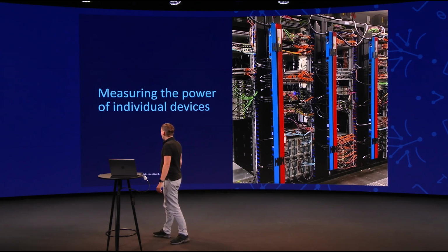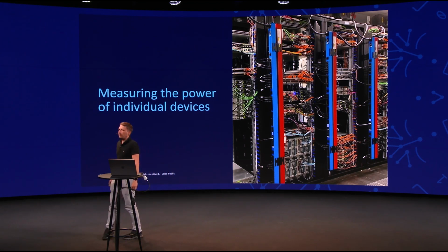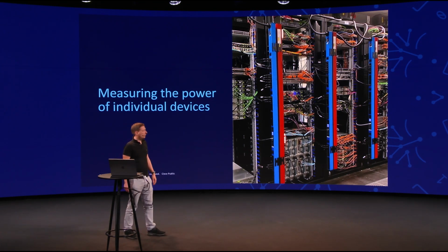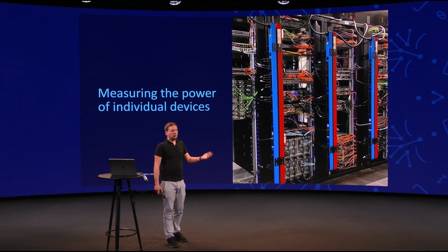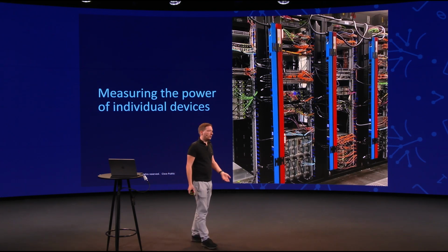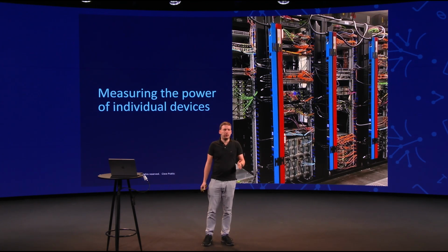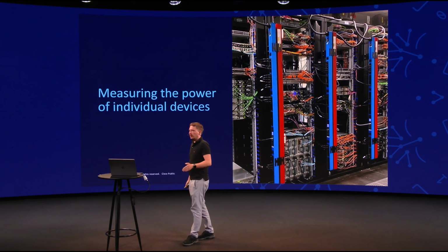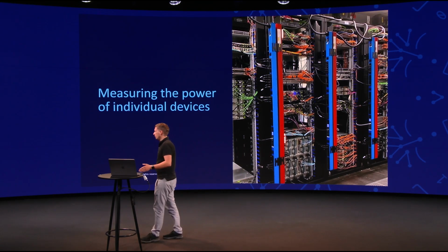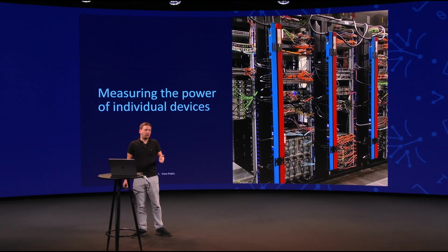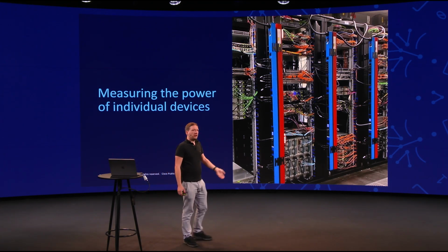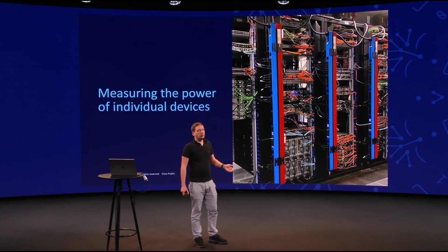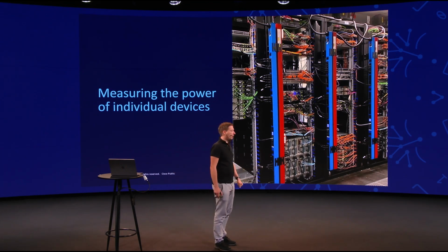But we have to maybe take a quick step back on power versus energy, right? These sensors that we talked about here are power sensors. And what I mean by that is, they can tell you my device is currently consuming 600 watts or something like that, at that very second. But they will only tell you what the device consumes at the time that you measure it through the sensor. They cannot directly tell you my device consumed 20 kilowatt hours over the last hour, or 20 kilowatt hours over a day or something like that.